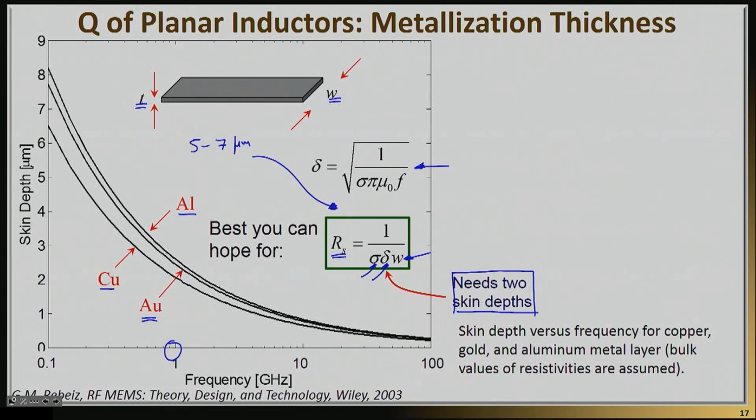And that's hard to do. And so the way we basically do that is by typically electroplating our metal to the thickness that you see here. But it also teaches you that once you reach 5 to 7 micrometers, any additional thickness you electroplate is actually useless. So that basically works from both sides. So if somebody tells you how thick something should be, this is a good way to explain that.